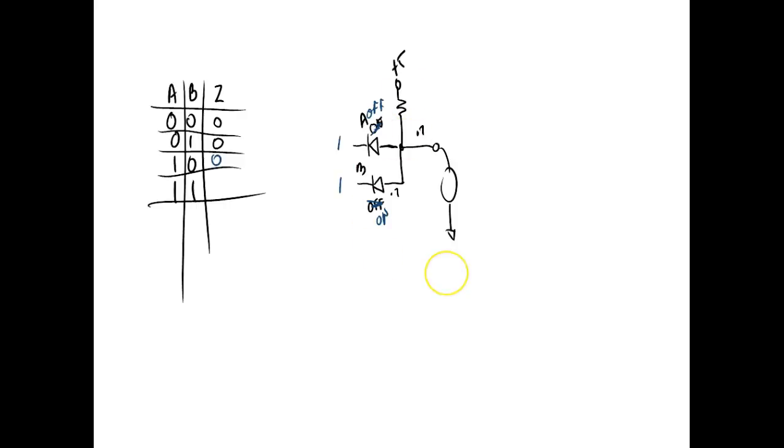So I'm going to come up here now, and I'm going to do this. Now, okay, what's going to happen? This guy's going to turn off. This guy right here is going to turn off. What's the output going to be? Well, now there's no current flow through this resistor anymore. So every time from now on, we've got current flow. Now there's no current flow through that resistor. So how much voltage is it going to drop? Huh? It's going to drop 0. So that means if 5 volts is right there, this guy drops 0, what's going to be right here?